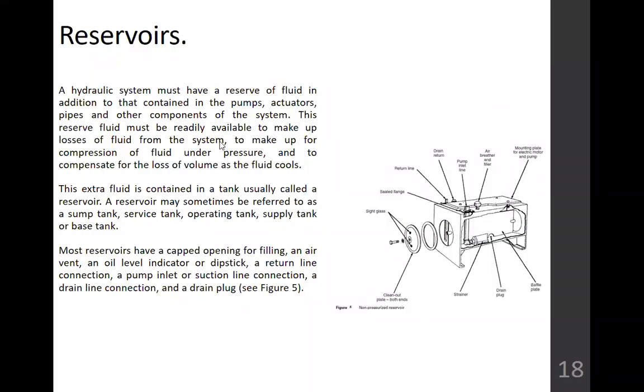A hydraulic system must have a reserve of fluid in addition to that contained in the pump, actuators, pipes, and other components of the system. This reserve fluid must be readily available to make up losses of fluid from the system, to make up for compression of fluid under pressure, and to compensate for the loss of volume as the fluid cools.